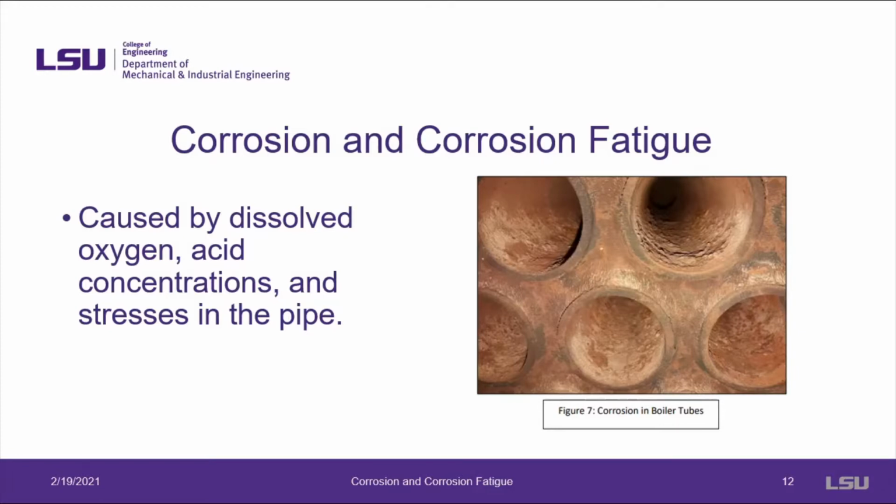Metals, whether that be in the boiler tubes or in the pipe connecting the deaerator to the boiler, will have a stronger tendency to corrode when stresses are applied. This is because corrosive elements can fill the cracks caused by the applied stresses and cause the metal to corrode faster and in some cases fail. This tendency is known as corrosion fatigue.